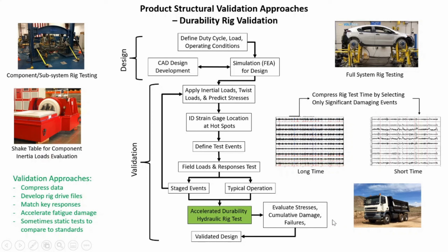And one other thing that probably should be mentioned here is nearly always this is dynamic. But there have been times that we've actually done durability rig tests where we're actually putting static loads on based on either measurements we've made or sometimes certain industry standards, and then examining the stresses that result with that and comparing that back to the simulation models that may have been previously used in the design of the structure.